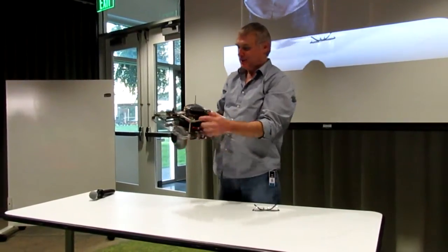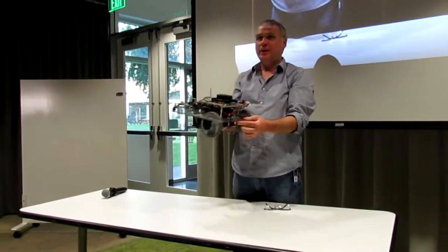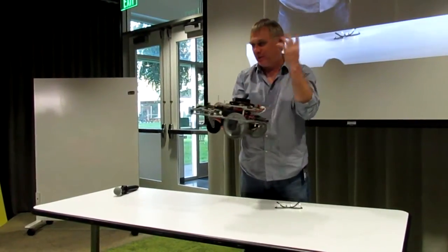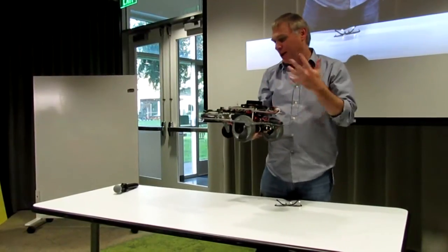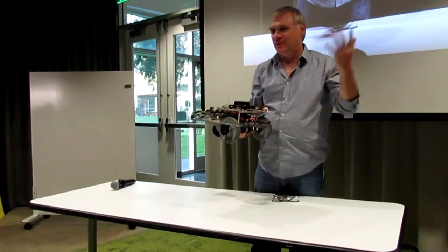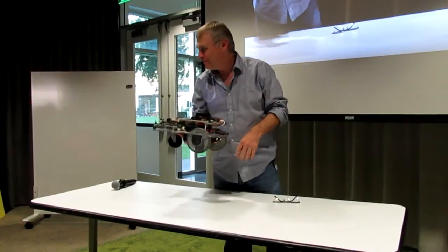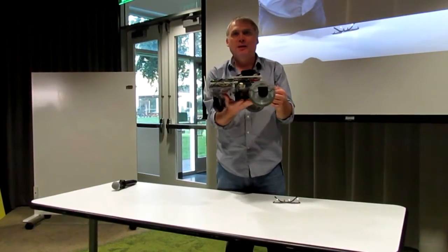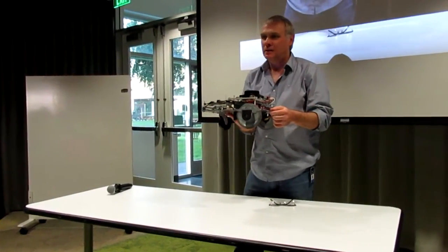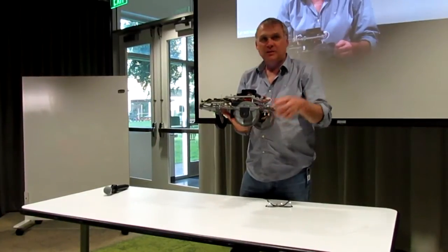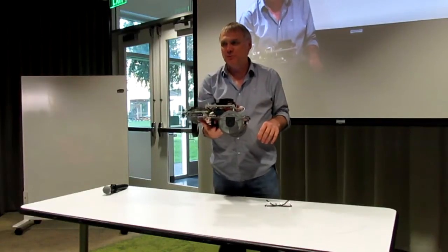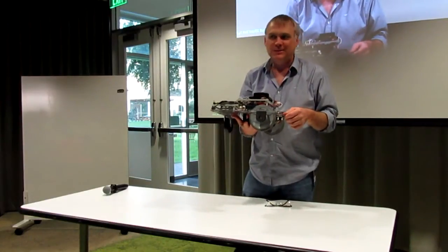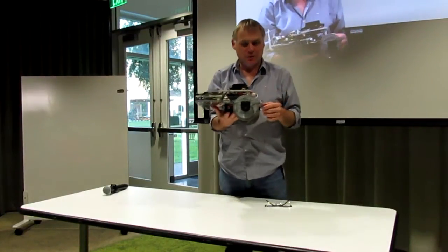So you'll see it's actually powered up, and it has a Neato LiDAR on it now that's scanning. I just cannot get the Wi-Fi to work as usual. I got a connection, but when you run ROS, it says it's trying to find localhost instead. There's some weird thing for the naming or something. I set my laptop up as an access point, and it does the same bug every time. It connects fine to my home router. Promise by next month I'll actually have it working.